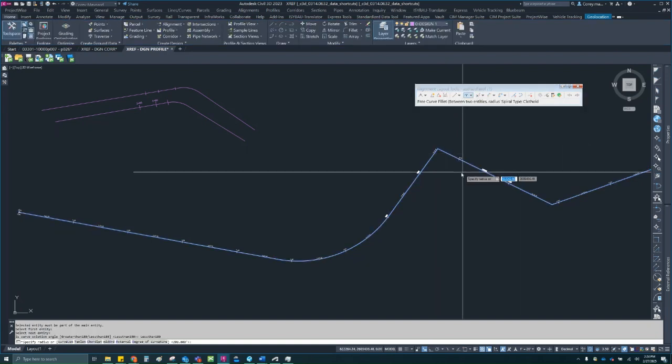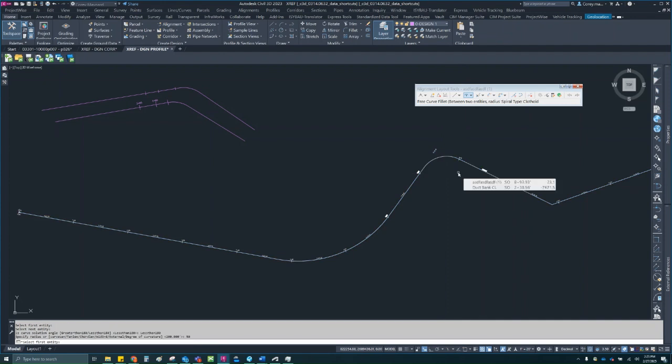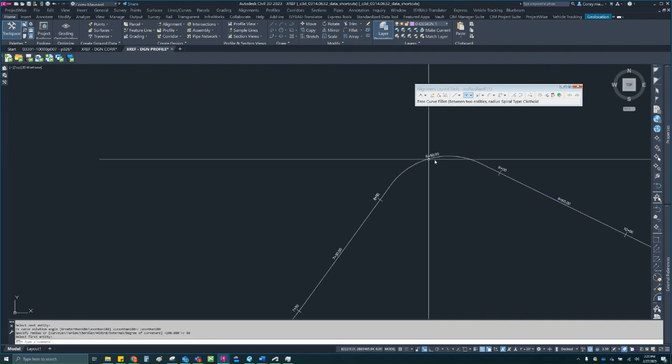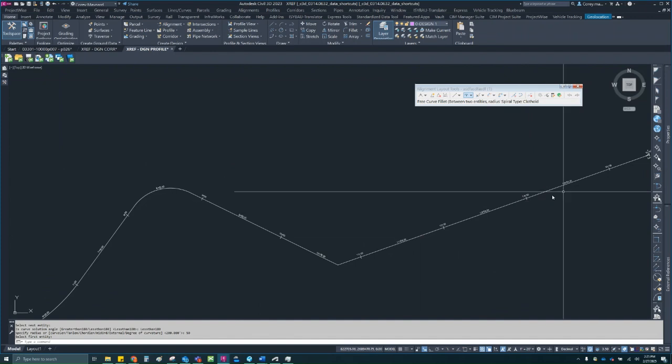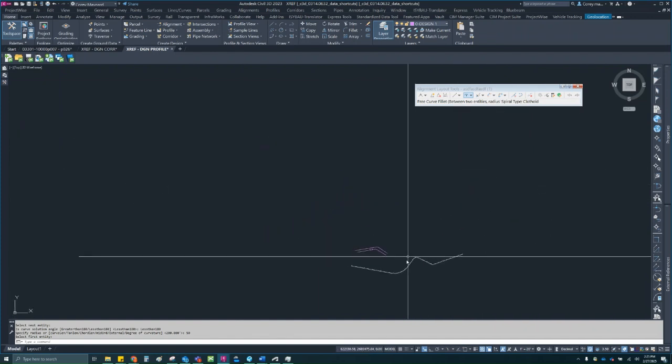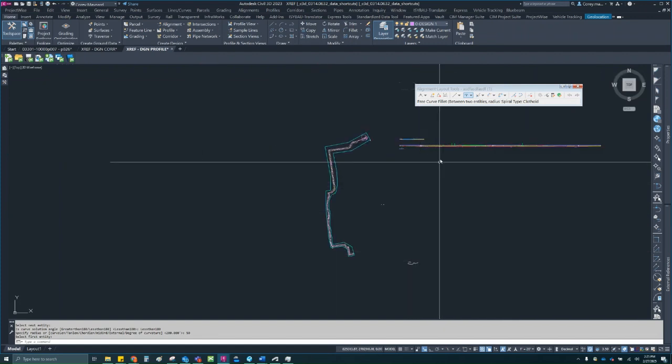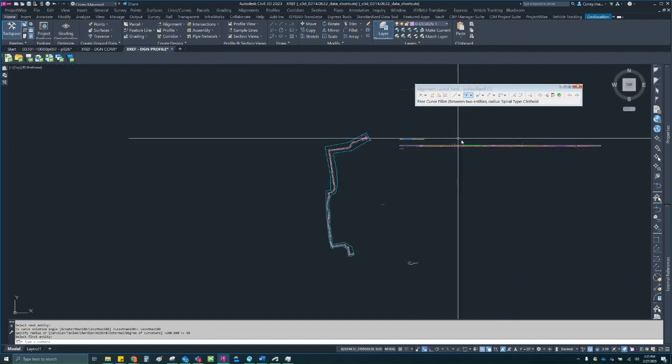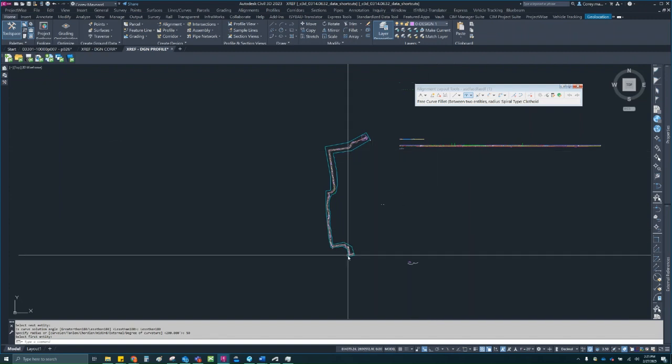As you can see here, let's add a 50-foot radius curve. Boom, everything updates. Everything downstream of that will update. Not only will it update here, but the profile views that are being created from that alignment, they will update automatically, and all of the items inside of that as well.